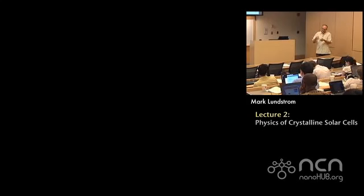Now, the right answer to that is to learn Shockley-Read-Hall statistics. There's a famous paper that was written probably in the 1960s about recombination through defects, and that's usually the starting point for this. But the way to think about this is that this defect has to capture an electron, and that's described by an electron capture time, tau sub n. But then to recombine, it has to capture a hole, and that's described by a hole capture time. So the time it takes to do the entire recombination process is tau sub n plus tau sub p. So the effective lifetime would be the sum of the two lifetimes.